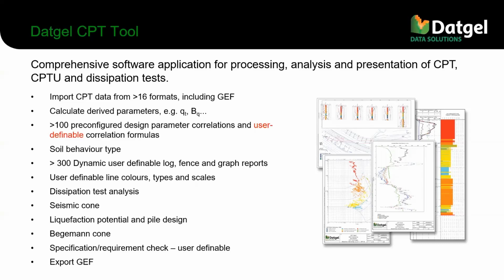It does dissipation test analysis to the point of calculating CH and CV. It can present seismic cone data, but we're not doing any special calculations on it. It can do liquefaction analysis and pile capacity analysis calculations. It has tools to check against specification requirements. And most recently, last year, we developed export to GEF 1.1.3, which is the latest version.